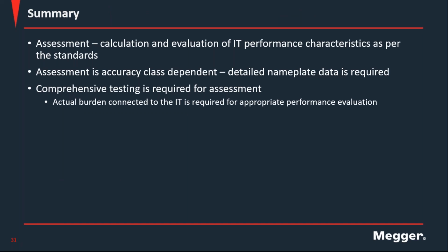So to finalize, the assessment is a calculation and evaluation of the instrument transformer performance characteristics as per the standards. It is class dependent, and you need detailed nameplate information. You need to provide accurate information to the instrument or the software for it to be able to evaluate against the standard properly.